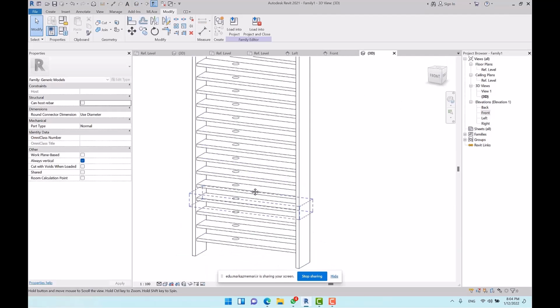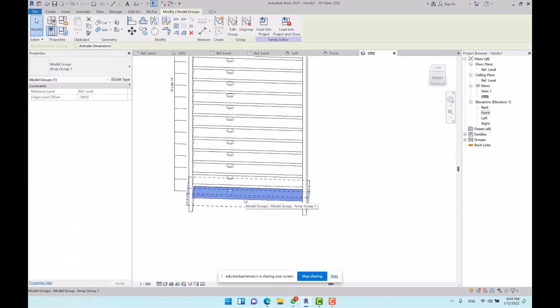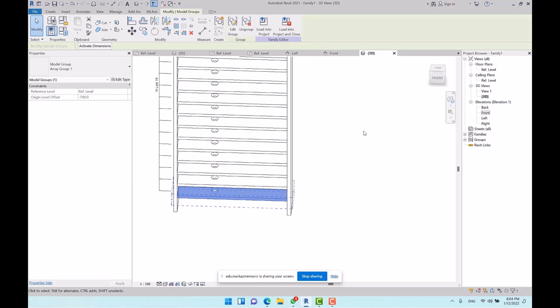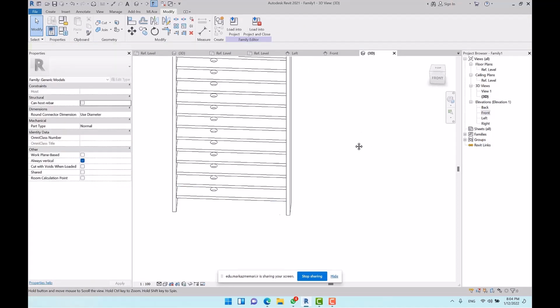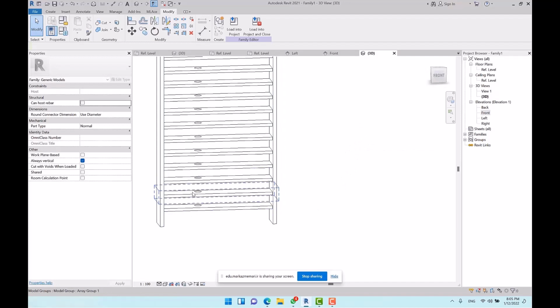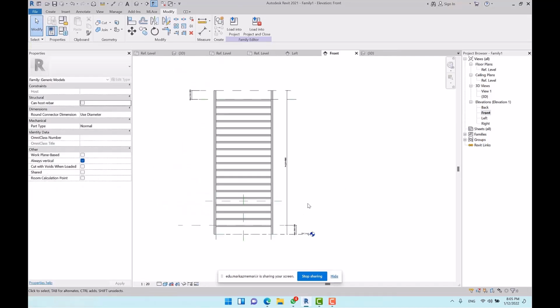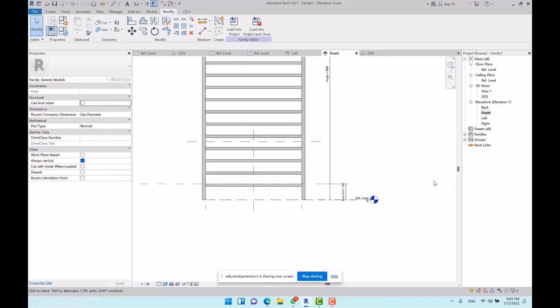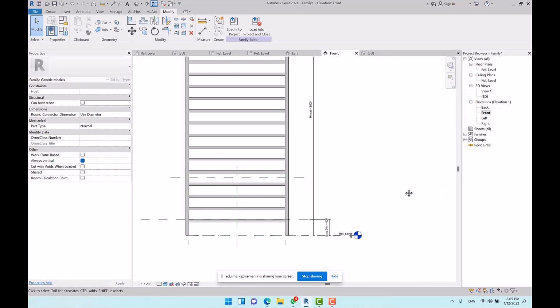But about the openings and the panels, let's check it out and create something with the holes. Maybe we could create a creative object. Just like the panels that we created in a separate file and then loaded here as a nested family to use inside the existing family, I prefer to create a column which passes through the holes or the openings, but I want to create this column as a nested family and then load it here.